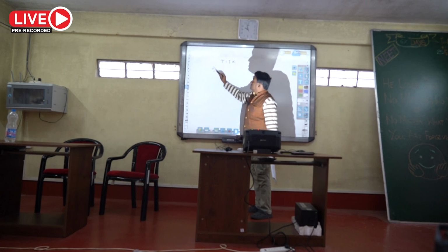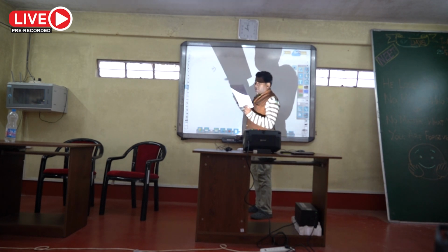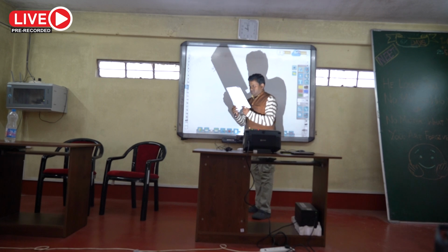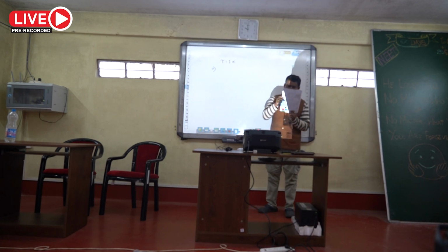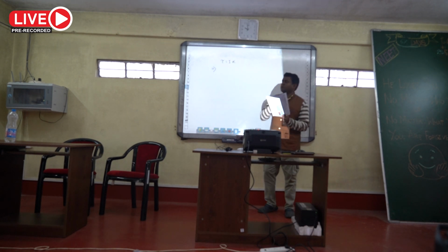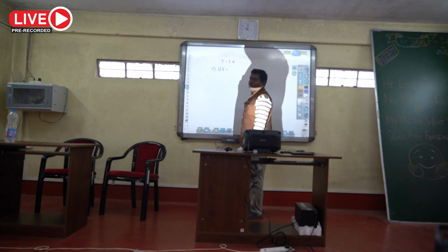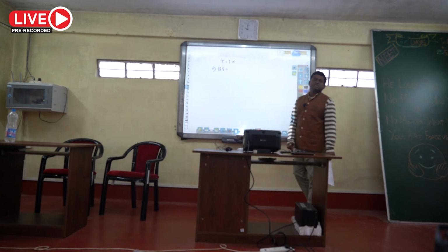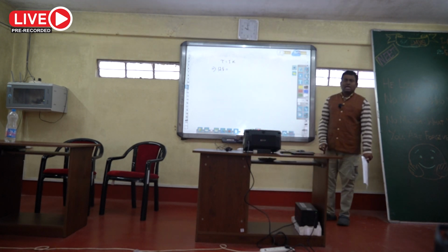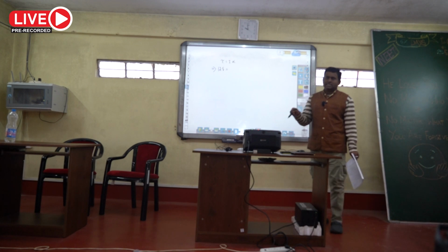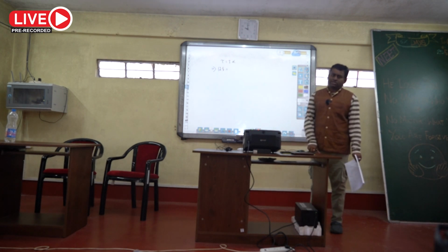Now torque is produced by constant torque. Constant torque is 12.5 Newton meter, that is 12.5. For the calculation of I, nothing is required because radius of gyration is given, and m k square, where k is the radius of gyration, is the moment of inertia.